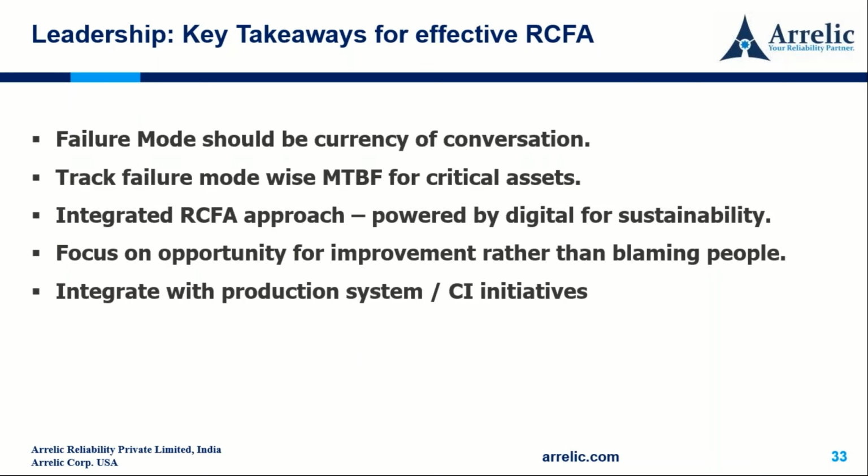Now, key takeaways for effective RCFA from a leadership standpoint. Failure mode should be currency of conversation. So we should be able to talk about them. Track failure mode wise MTBF for critical assets. What is MTBF? Mean time between failure.